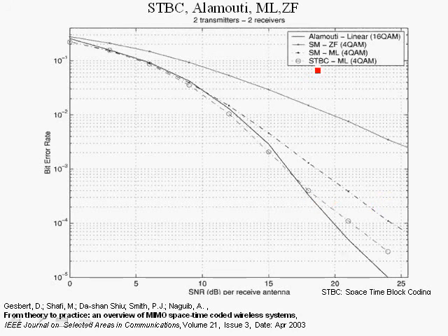If we take a look at the Alamouti scheme, which is a solid curve over here, the Alamouti scheme is using 16 QAM because the Alamouti scheme is not using spatial multiplexing but transmit diversity with one spatial stream. But since we get a diversity gain, we have a higher signal to noise ratio, so we can actually transmit a 16 QAM signal through the system.